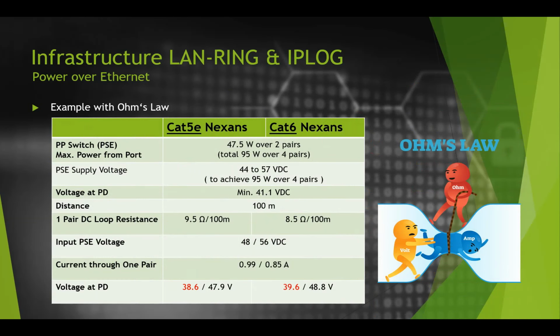A frequent question is the maximum possible length of the cable with PoE power supply, especially with PoE above 60 watts. With these performances, the resistance of the cable and the resulting voltage drops must be taken into account. In order to achieve sufficient voltage at the PoE PD device input, it is therefore necessary to use sources with a voltage higher than 48 volts. That's why we have series sources in our offer that allow setting up to 56 volts.